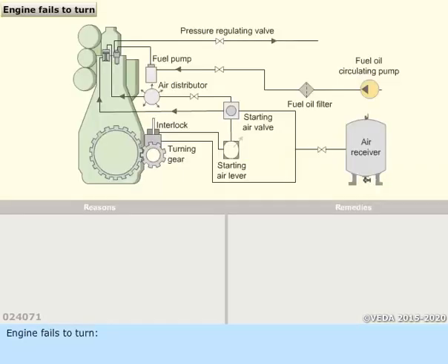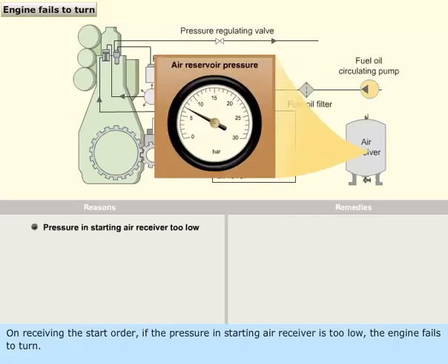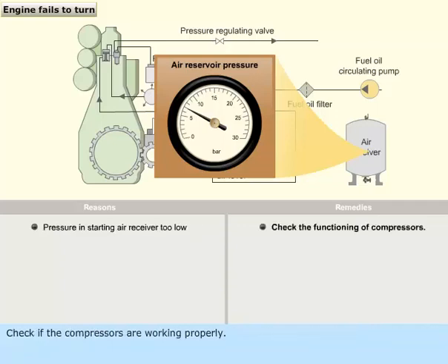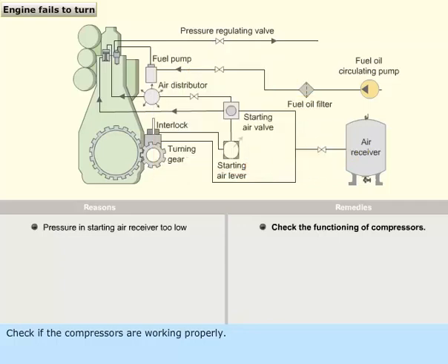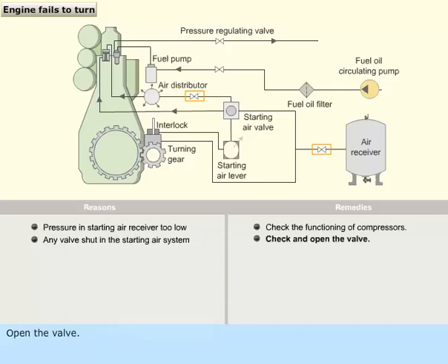Engine fails to turn. On receiving the start order, if the pressure in starting air receiver is too low, the engine fails to turn. Check if the compressors are working properly. Check if any starting air system valve is shut. Open the valve.